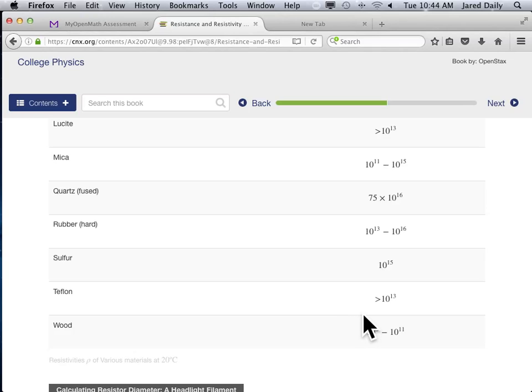It just does not allow current to flow. Would fused quartz be better? Yes, but fused quartz is very brittle and harder to work with in small sizes, because you want it to be very small and thin. Teflon is easy to make small and thin, you just stretch it. Fused quartz doesn't do that so well.